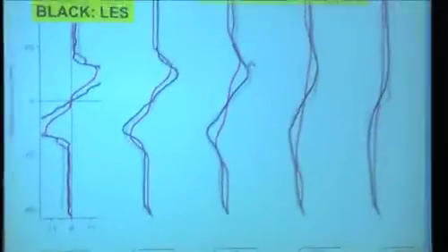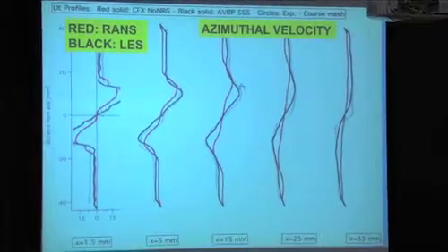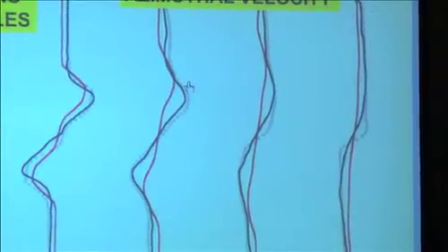And you look here at the azimuthal velocity, it's the same. The RANS formulation just misses the swirl, basically. And the other problem, which is classical with RANS, is that since it's too dissipative, it kills the vorticity, it kills the mean velocity. You see here, it's not swirling anymore. This result is very close to what I've shown you yesterday. If you use RANS, it kills eddies. And the swirl is just another eddy. Okay? The swirling flow is just another vortical structure. So it's dissipated, again, by turbulent dissipation, turbulent viscosity.